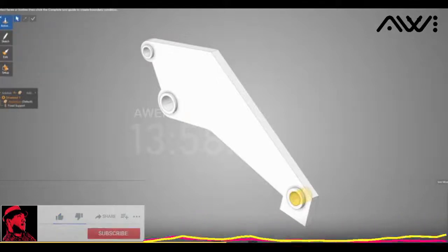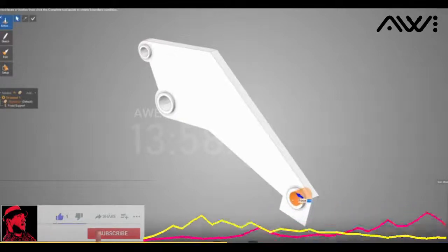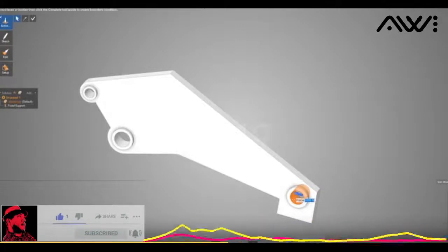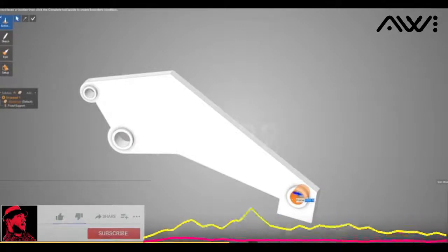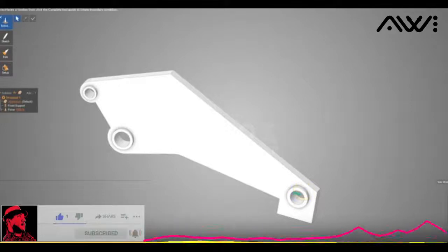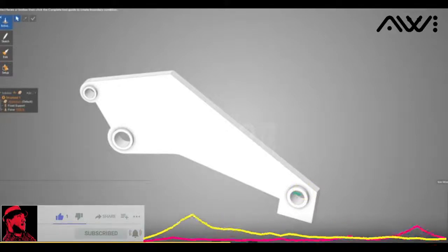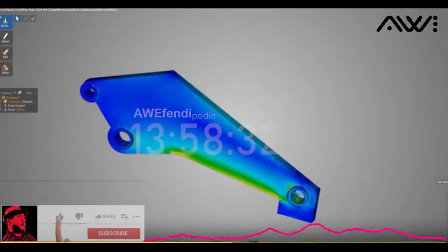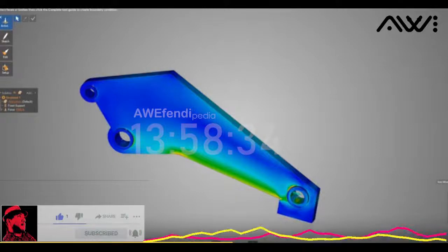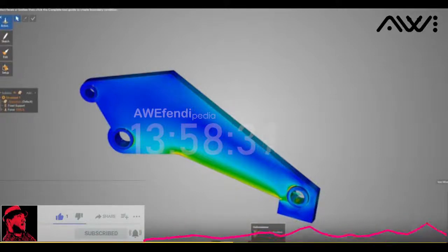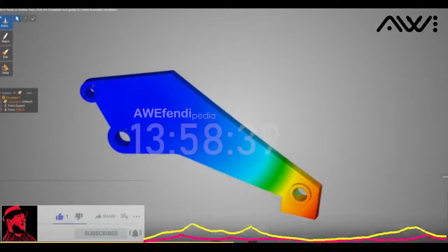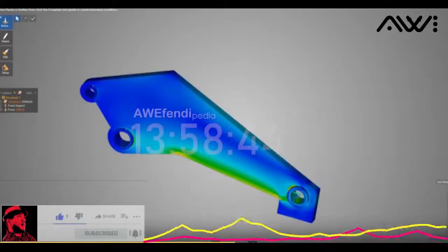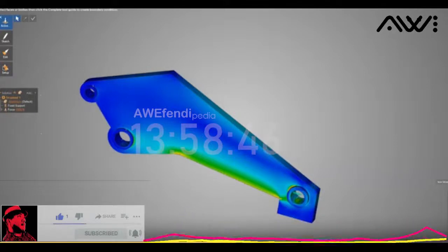And this is where my force is going to be, for example, right? So let's go with maybe 1,000 newtons, right? Key that in. And if I click on the head of the arrow, it flips the direction if you want that. And now we have this, right? So if I go ahead and hit play, what we're looking at right away is just stress, right? Okay, well, getting some feedback instantaneously. What's kind of the deformation going on? Let's look at what's going on there. Okay, that makes sense. The force and the stresses. Okay, we're getting somewhere here, right? But let's now do topology optimization.